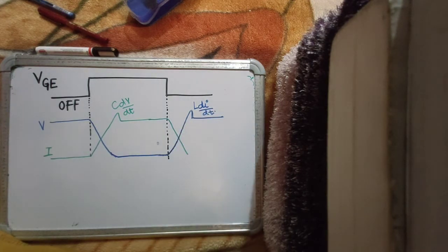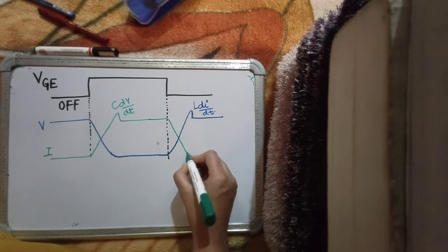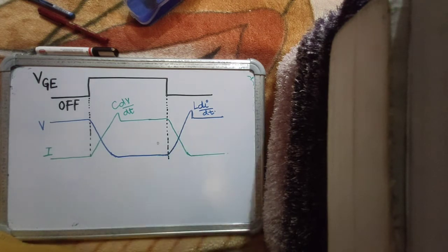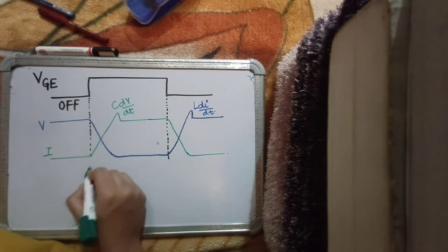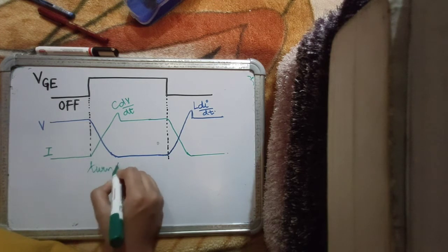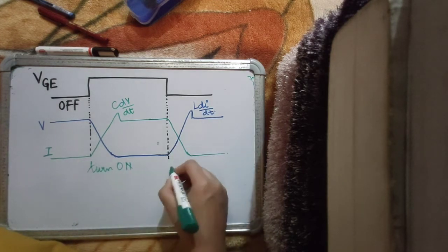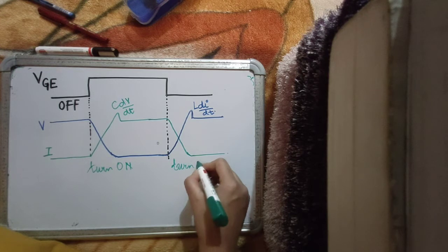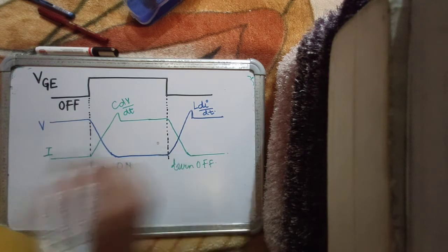We have discussed this previously in our initial lectures when we started with gate driver design. We basically started with understanding the behavior of a switch, and even in Snubber circuits we have understood this concept. So capacitances are bad during turn on and inductances are bad during turn off, right? This is what we know so far.